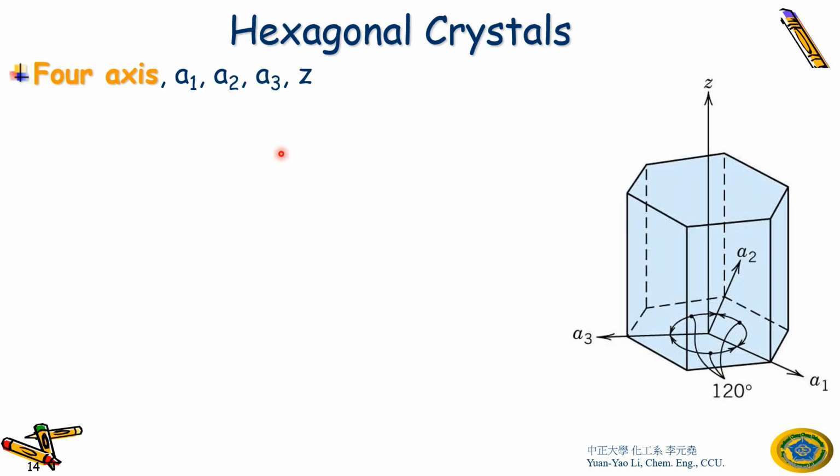Okay. But before we talk about this, I hope you remember we talked about another one called hexagonal crystal, because BCC, FCC, and HCP, right? And FCC actually is the same as HCP, but different packing sequence. One is AB, AB, one is ABC, ABC, right? ABC, ABC is for FCC, AB, AB is for HCP.